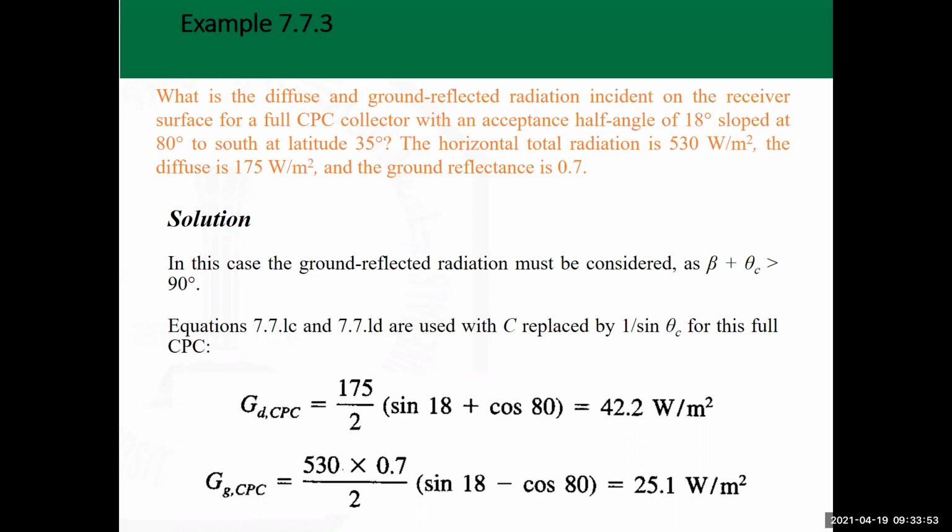The good thing about the program is that it may do a parametric analysis for you. Meaning what? Meaning that on the screens, it will give you a recommended number of collectors to be used for the city that you have. Do you have to stick to that? The answer is no. Suppose that you have taken a case and it has recommended 14 collectors to be used.